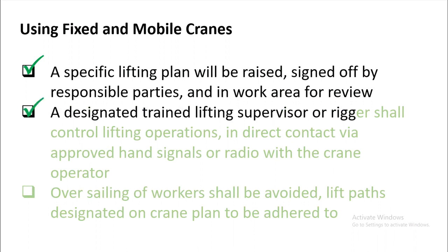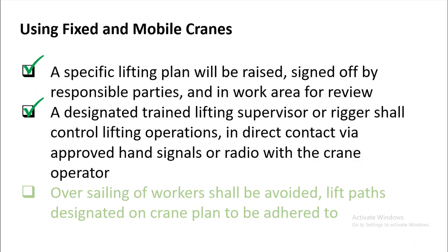A designated trained lifting supervisor or rigger shall control lifting operations in direct contact via approved hand signals or radio with the crane operators. So make sure you have a dedicated lifting supervisor on your lifting operations.